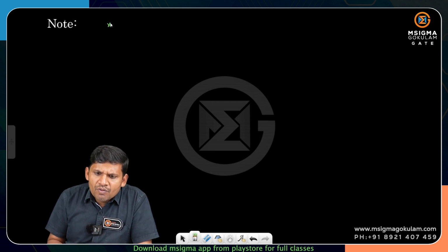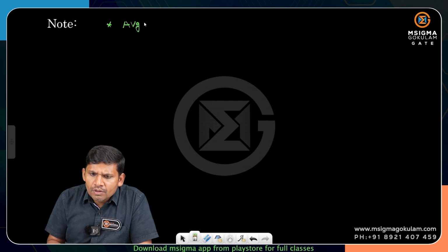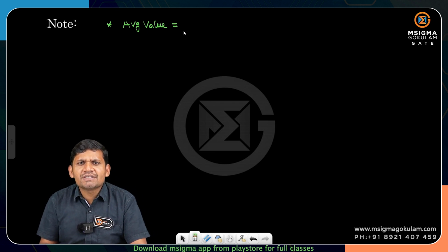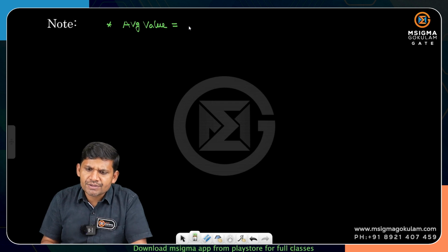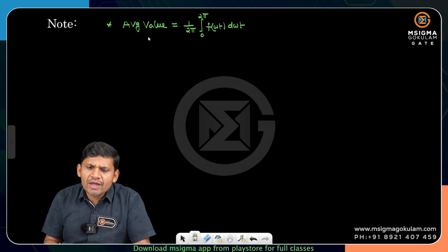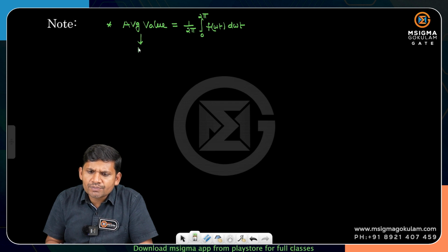First I am writing how to find the average value for a given function. If any function is given, the best method of calculating average and RMS values is the integration method, students. That I am writing: 1 by 2 pi integral 0 to 2 pi f of omega t d omega t. What is another name for average value, students? It is also called mean value.